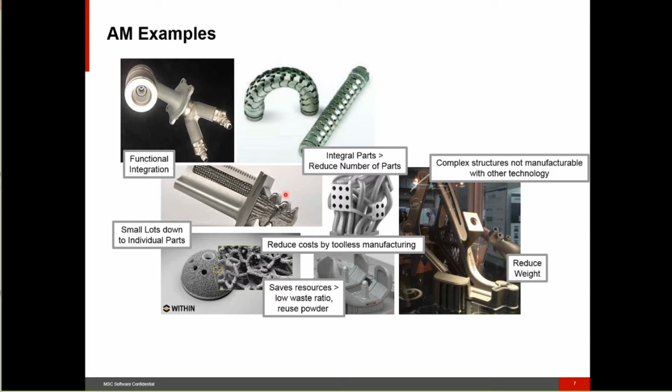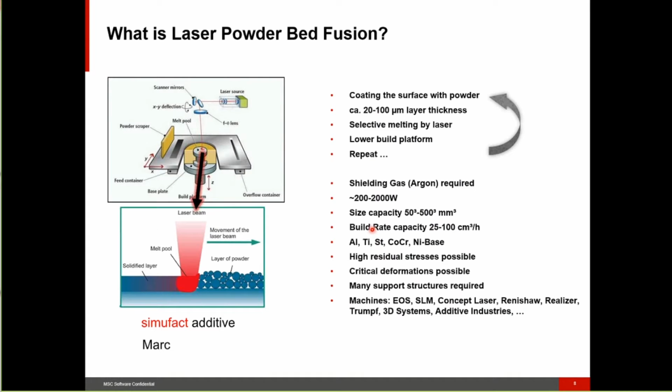Turbine blades are nice to be able to achieve because we can put cooling passages right into the blades. The use of cooling passages also makes this very appropriate for constructing dies. And one can see that you can really form very intricate geometries, which before you would have done through bending different pipe sections and then, of course, welding or brazing them together. Lots of innovative designs are coming in through additive manufacturing.